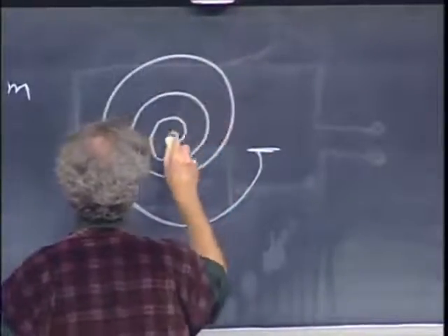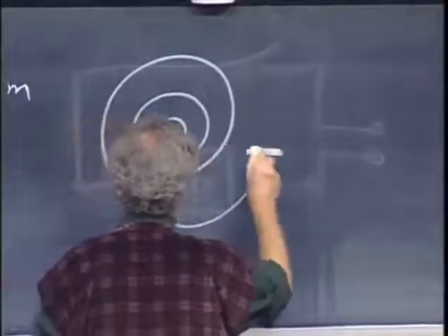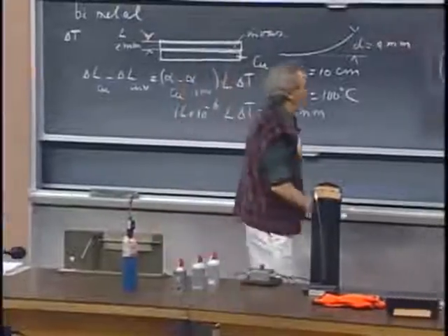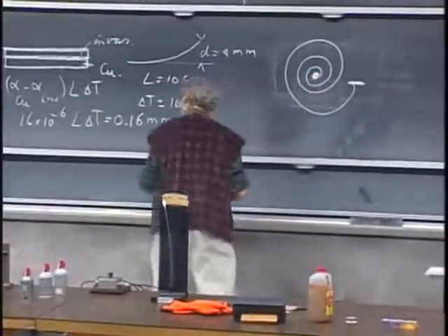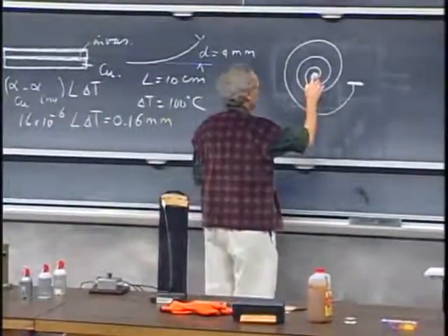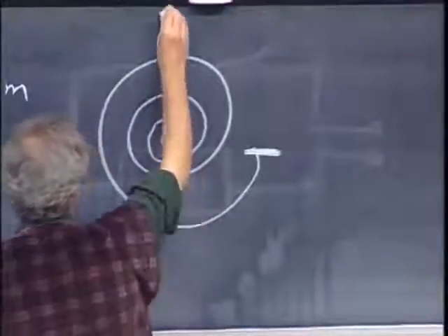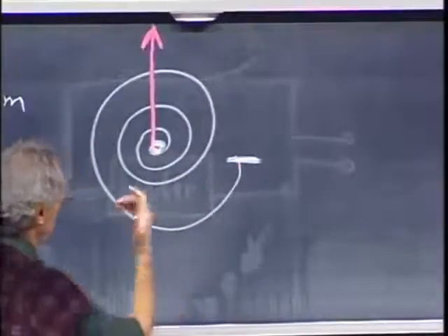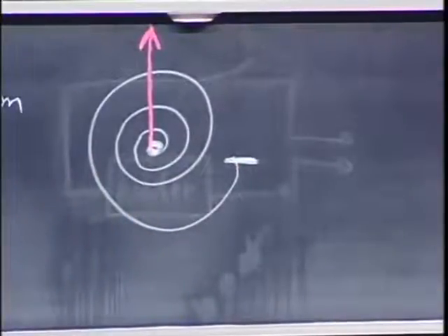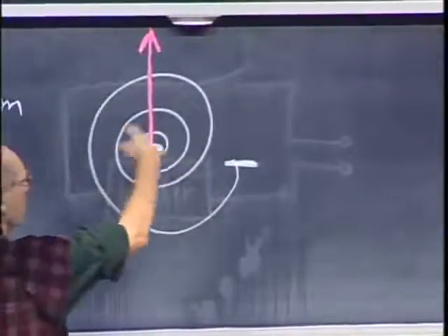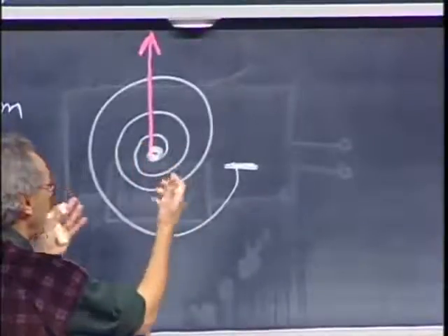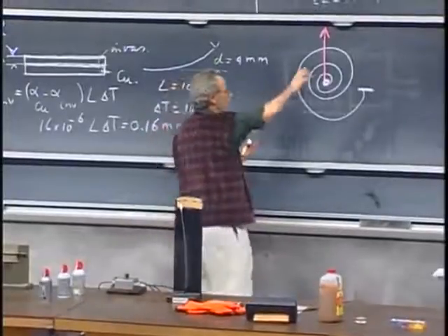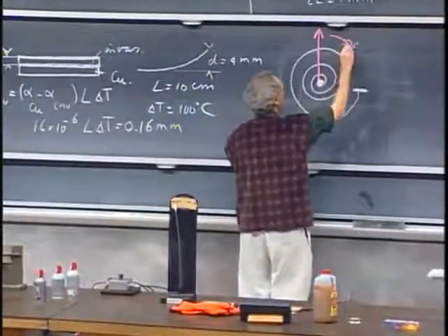There's a coil. This end of the coil is attached to the plastic casing. And here is the red hand. It's a pivot here. It's a red hand. So this is fixed. This cannot move. I heat it up. What will happen when I heat up? This is already a bimetal. It's already curved. But when I heat it up, it will tighten even more. It will curl up even more. And when this one curls up even more, it will go into this direction.